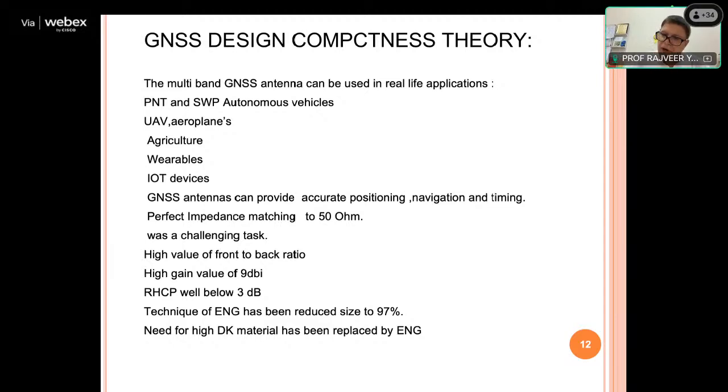Otherwise, I was dependent because as far as the Indian scenario is concerned, there are two companies, High Tech Bangalore and Sramik Ahmedabad. These two are able to supply me the dielectric constant material for devising dielectric resonator antennas, which has a low permittivity, that is 10.8, 9.9 only. We are already aware that epsilon, or relative permittivity of a material, is inversely proportional to frequency.